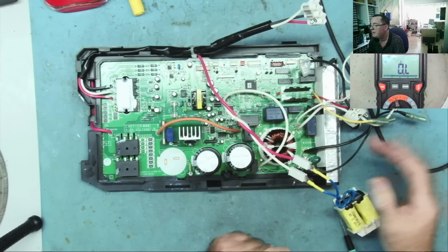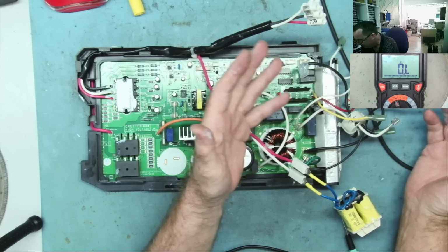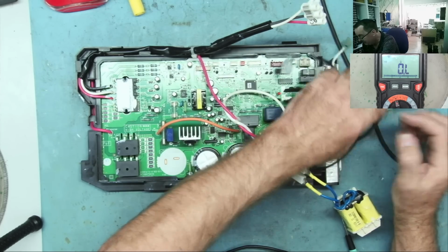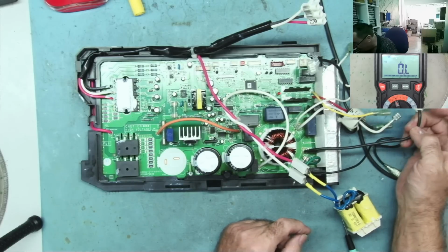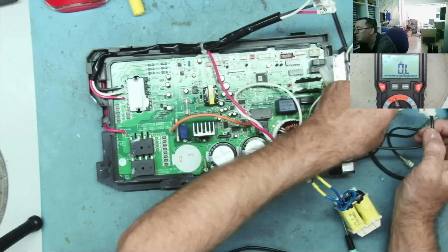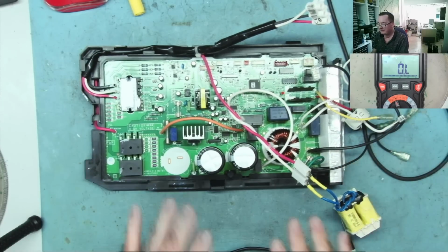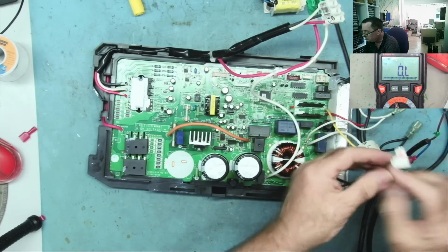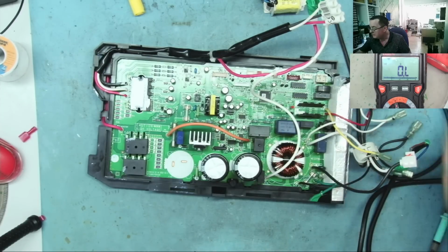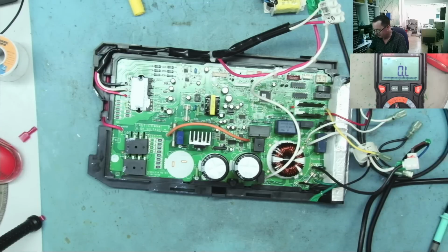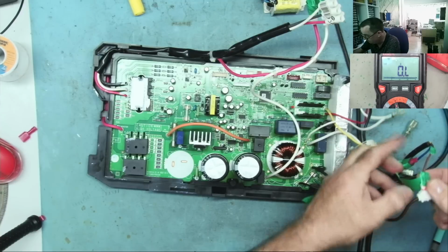The other thing I want to make sure of is that none of these wires touch anything else, because I don't know where there might be power on any of them. We can see the input wire, so we know where the power comes in on this black one and on the white one. So I'm going to put a bit of insulation tape around these various connectors so nothing accidentally shorts together, and then I'm going to power this up. Okay, so I've connected the power onto this. I'll just put a little bit of insulation tape around here as well, just to keep that in there so it doesn't touch anything as well.